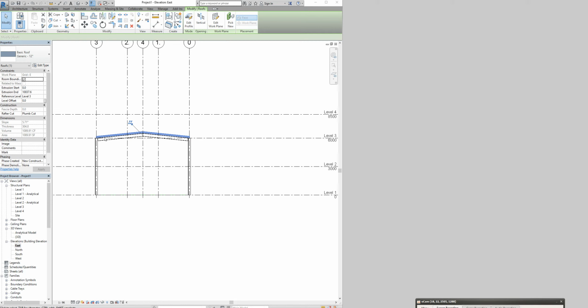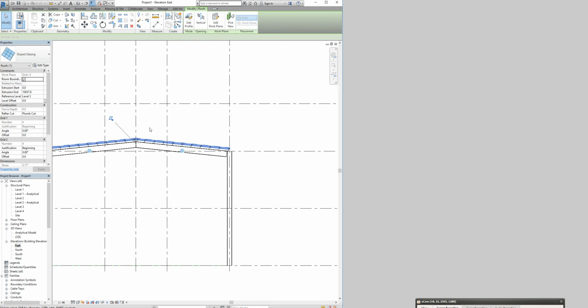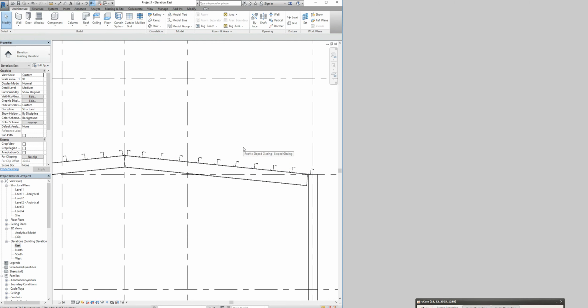Change roof properties to slope glazing. So we just go here, slope glazing. Modify parameters of slope glazing as shown below. Well, we modify the parameters, so edit type. We have modified parameters before, so they should know that parameters are in edit type by now. So we just go to curtain panel, empty, not defined, none, layout, fixed distance here, and then 500 spacing, sorry, 500, none, and here rectangular. So it's just the family we just created, which is the set purlin. Set purlin and set purlin. Okay, apply, okay. So now we see our structural members to mount the roof here.